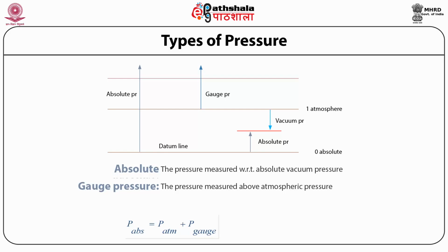In many drying operations, you must have heard about vacuum pressure, where the pressure is maintained in vacuum for efficient and fast drying of food products. The vacuum pressure is the absolute pressure in short of atmospheric pressure. If any pressure falls below the atmospheric pressure, that is 101.325 kilopascal, the shortage is said to be vacuum pressure.